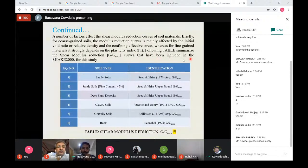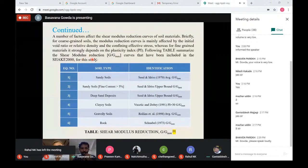Some of these shear modulus reduction curves are inbuilt in the Shake 2000 software, but you have to select a particular type of curve depending on what type of soil you will encounter. In Shake 2000, we give them as input as an equation number. If you just input this equation number, then it will select that particular curve. So for sandy soil, this is the curve.